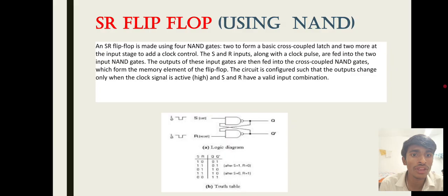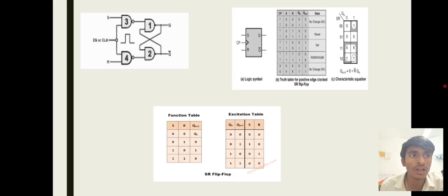The basic flip-flop has two inputs, R and S. It stores data by setting or resetting. It has an undefined or invalid state when both R and S inputs are high simultaneously. It is used for basic memory storage but limited due to the invalid input condition.